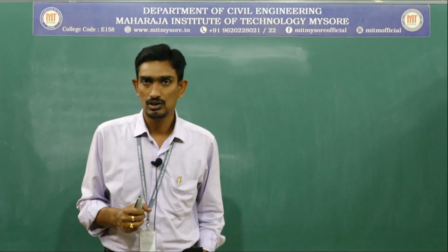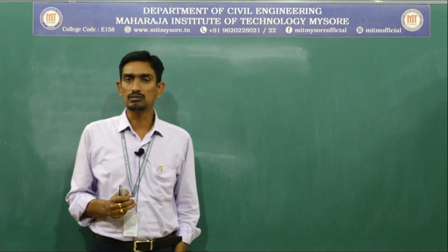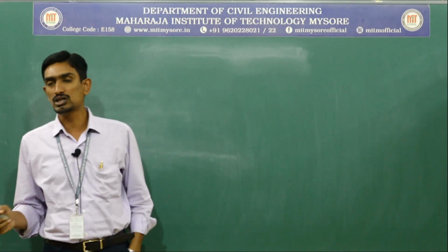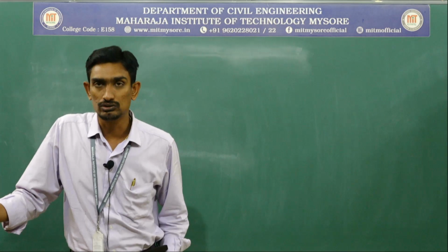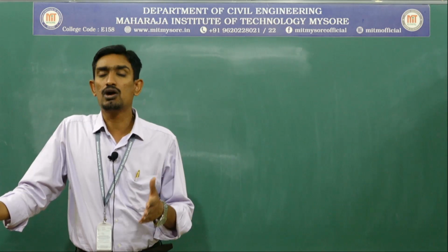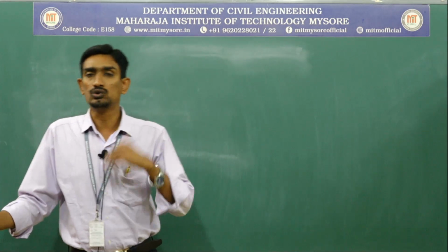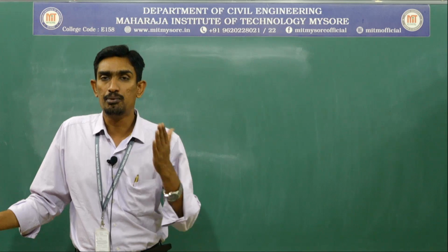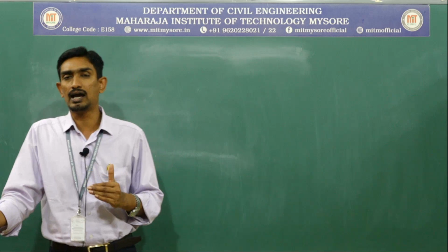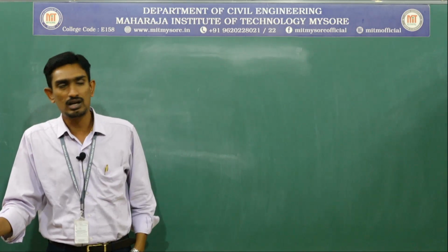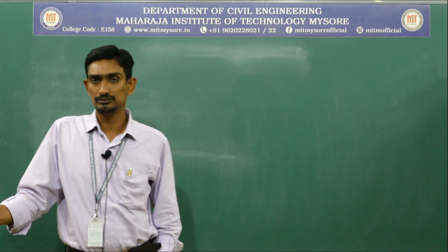This fly ash is a predominantly used pozzolanic material that can be used as the best replacing material for cement also. When I mix this fly ash, which is a pozzolanic material, with cement, it is called Portland pozzolana cement. There I can reduce the carbon dioxide emission. It is completely eco-friendly, a green product or green cement.